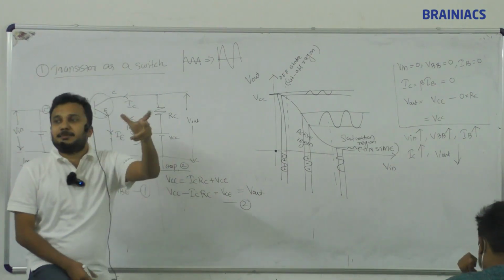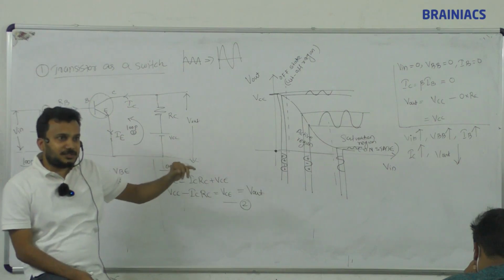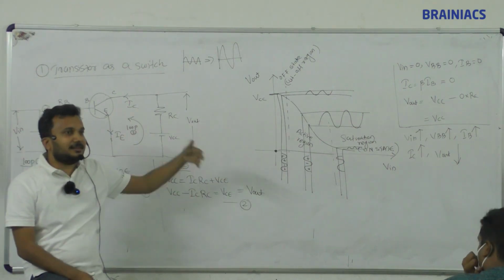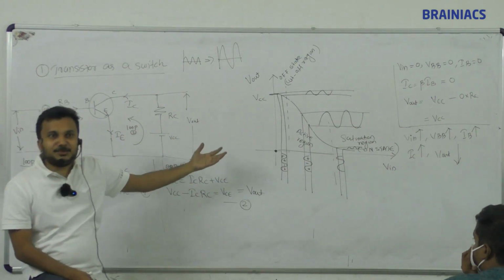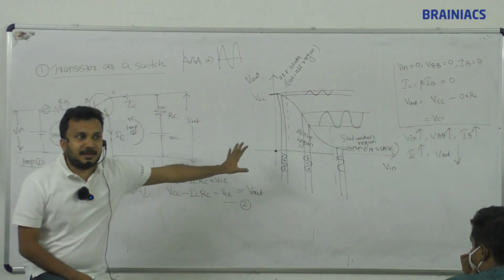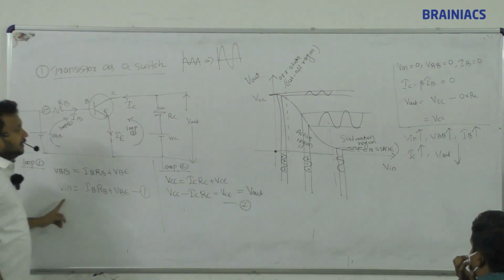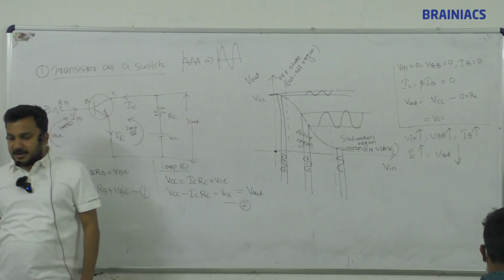So the transistor can be made use of in all three behaviors. All three behaviors have importance. In the off state and on state, the transistor can be used as a switch. In the active region, I can use it as an amplifier. So the transistor will work as an amplifier in the active region. Okay. So the next heading: transistor as an amplifier.